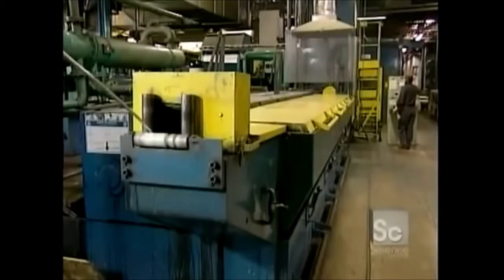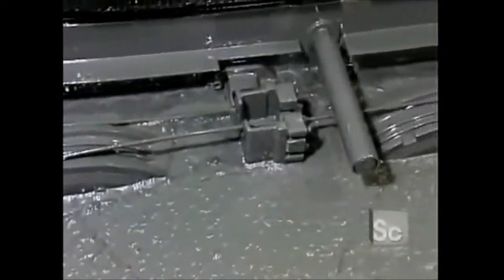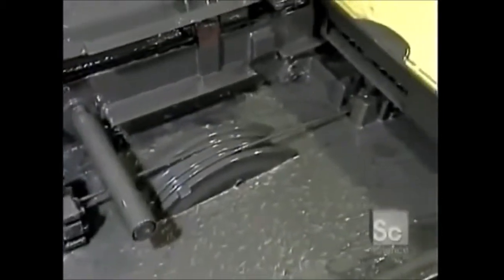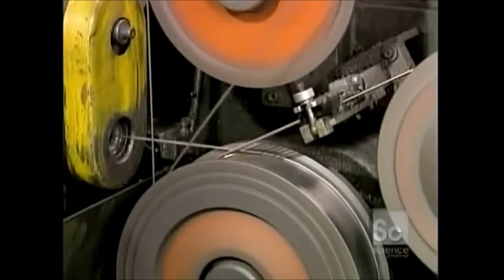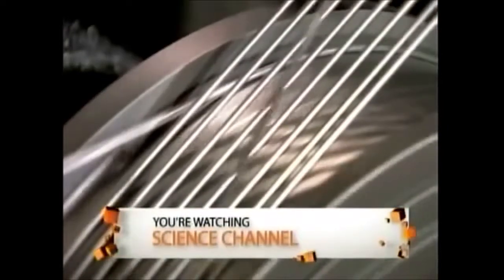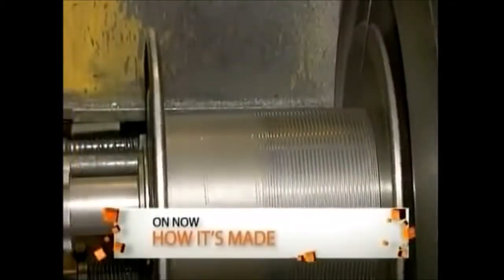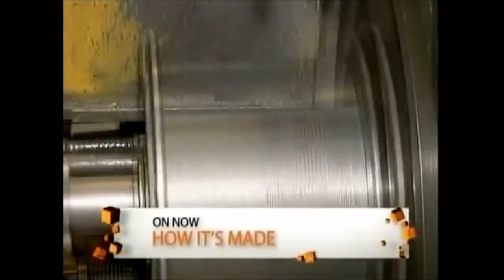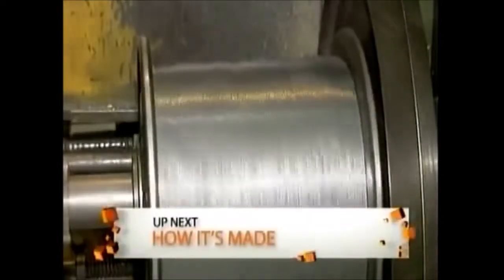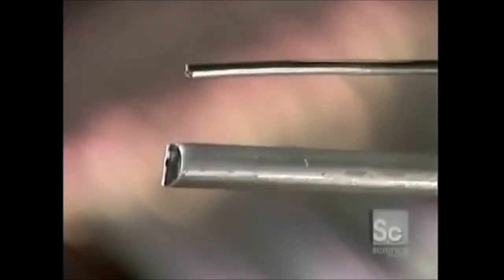They feed the rod into a machine that draws it out through a series of lubricated pulleys and dies, stretching, lengthening, and thinning it out, and eventually winding it onto a large bobbin. What was once a rod 4/10 of an inch in diameter is now just 8/100 of an inch, the width of about a dozen human hairs.